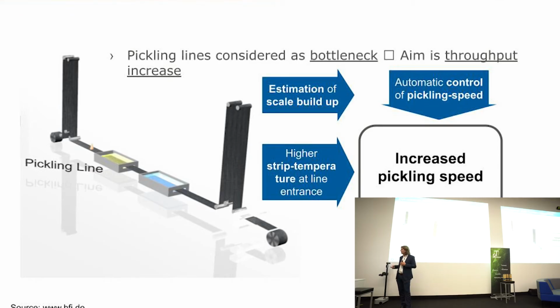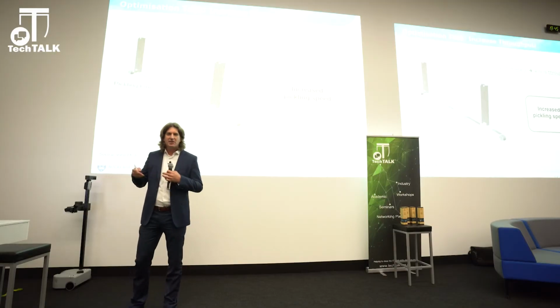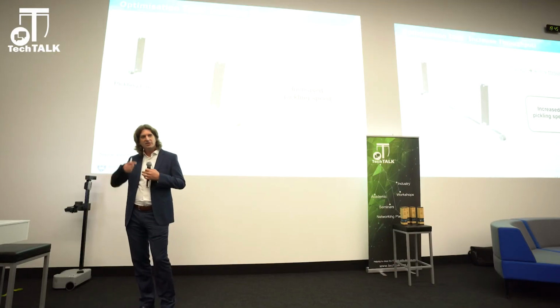And we decided if we want to improve that process, just for those of you who are not familiar with that, during the hot rolling, you reheat a slab, roll it down to maybe 4 millimeters, and then it's leaving that process at 650 degrees in a coil.